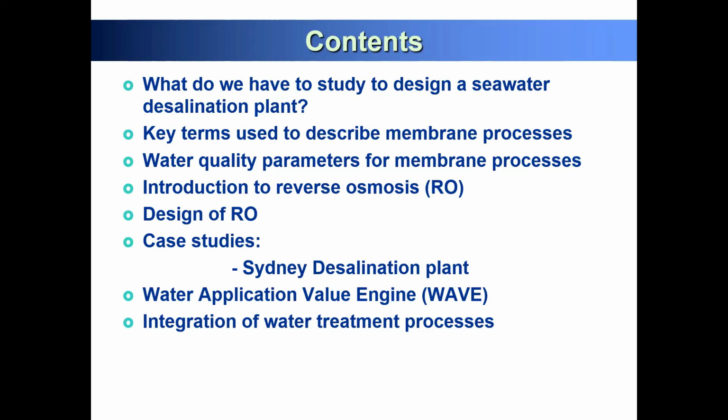Okay, we pressurize 10 bar, 20 bar, 60 bar, 100 bar. So what pressure can this module tolerate? At what pressure can we produce how much desalinated water? That's exactly what we have to look at in the design of reverse osmosis. So that's how we have to think about it. So it's like 250 million liters per day.